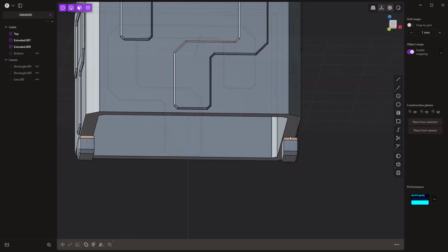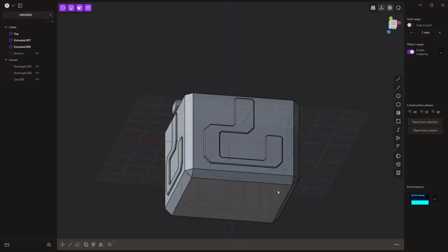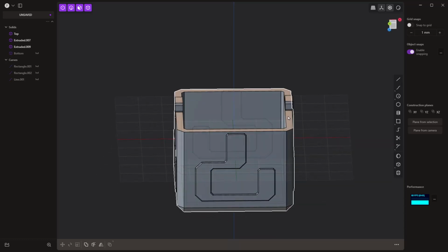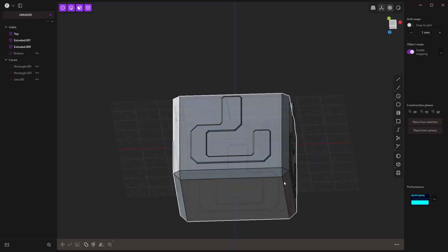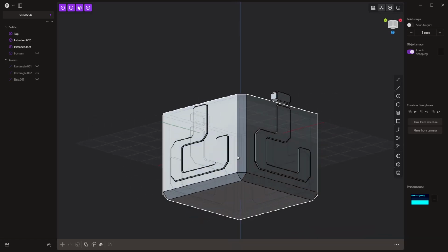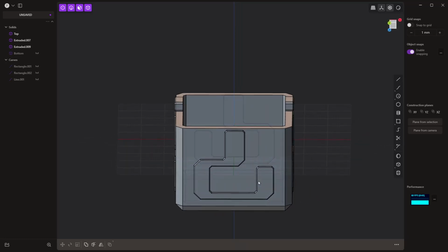When this thing gets 3D printed, it's going to print upside down. So we can print that thin wall coming up, no problem. And this bottom, because of these tapers or chamfers, that's going to print just fine. In most cases, most 3D printers will print 45 degrees without any issue. You don't need supports to make that work. And because the question marks are so thin, 0.5 millimeter with small bevels or chamfers on them, then we don't really have to worry about any supports there as well.